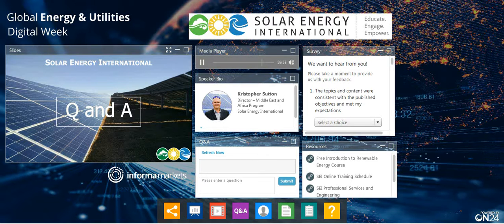So it's basically a battery-based standalone system. You would have a PV array to generate energy, a charge controller to regulate the charging into the battery bank itself, and then, depending on the applications, the traffic camera or any of the other systems you're trying to run, whether those are DC or AC is the next question.